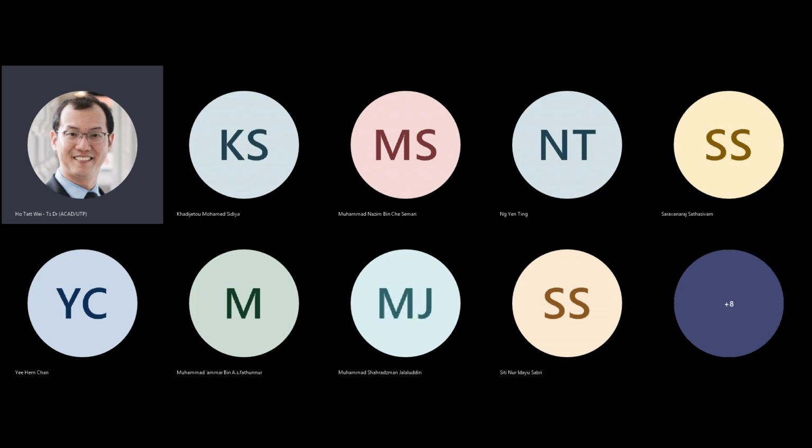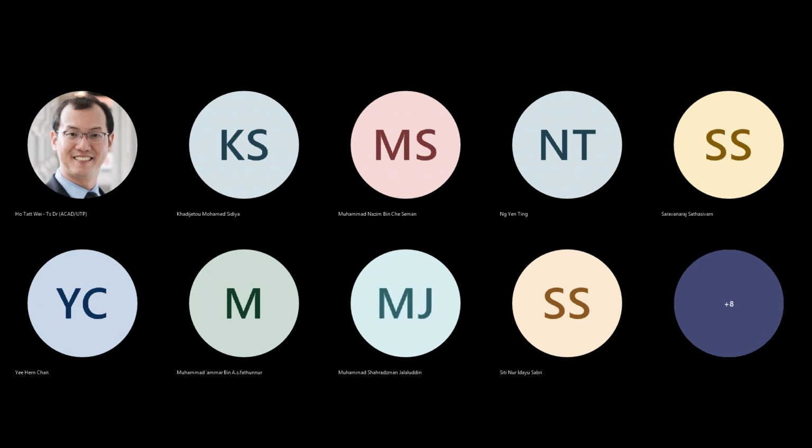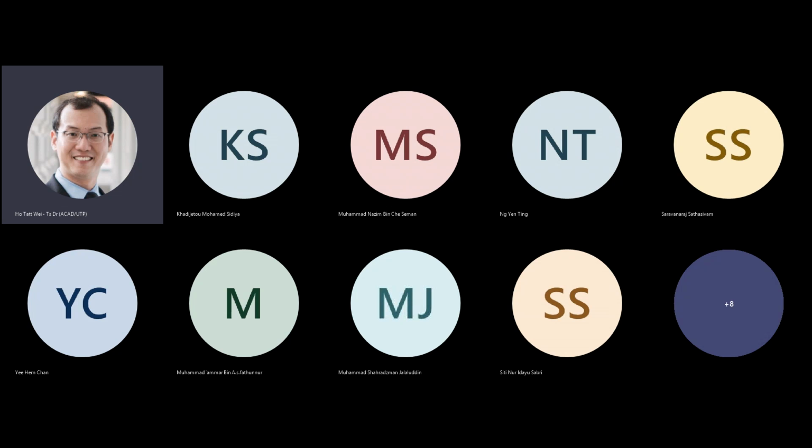Conversely, if C is 0, so C bar will be 1, then this value here would be dependent on the value of I0, right? So this two-stage logic, an AND gate followed by an OR gate, is an implementation of a two-input multiplexer. Of course, you also realize that multiplexers can be created with a 2-bit control, so it would be equivalent to a 4-input multiplexer. You can have an 8-input multiplexer, in which case there are 3 control pins, and 16 and 32 and so on and so forth. So you can implement them as a sequence of AND and OR gates.